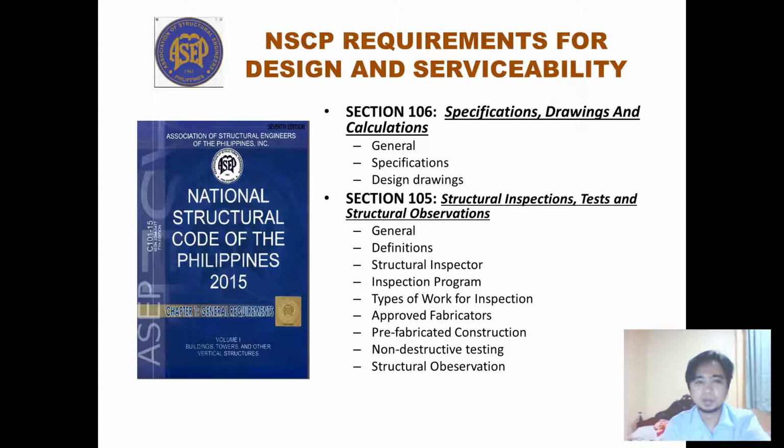Of course, what is in the design, for example, we have set a certain strength for concrete, meeting the strength requirement like 22.4 requirement for FC prime in megapascal, or a certain strength or grade 60 requirement for the steel bar. Of course, you wanted to assure that whatever in the design, it should be properly implemented.